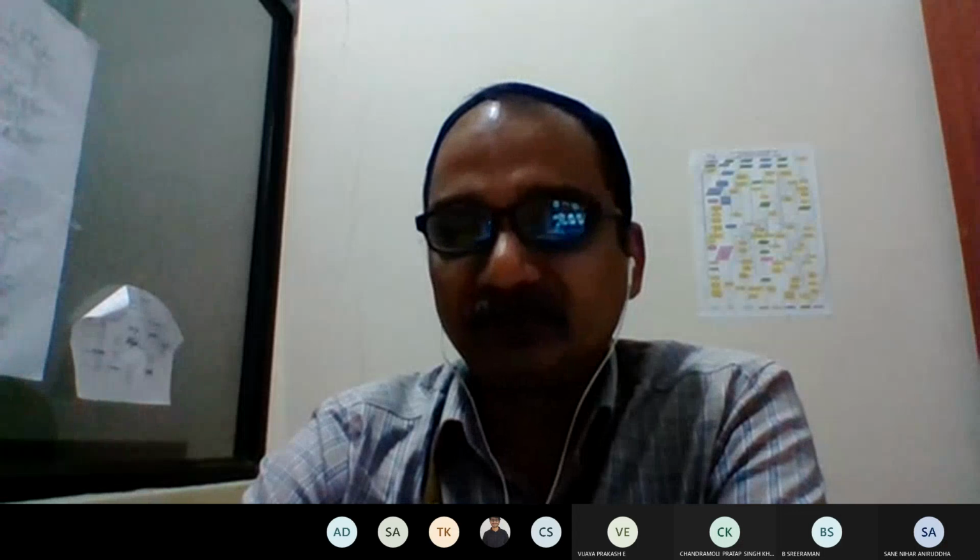In the last class, I showed you some equations for finding the temperature distribution in an infinite solid, which was called the infinite series summation solution for Fourier number less than 0.2, and for Fourier number greater than 0.2 you can use the first term approximation. I introduced that only so that you know what things are available.